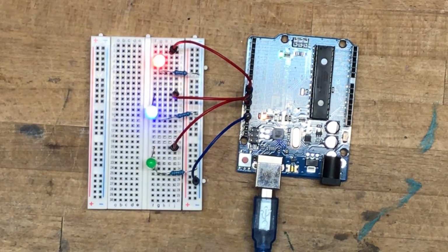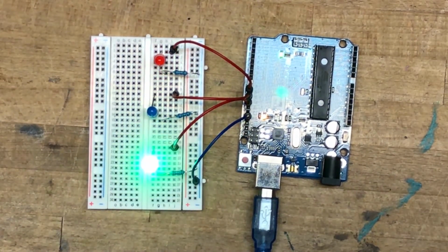So here's the operation of the next little piece of code. This is an example of 2 for loops working in conjunction. So in the last one, the run of the lights was red, blue, green, red, blue, green, red, blue, green, red, blue, green. In this one, it's bouncing back and forth. Red, blue, green, blue, red, blue, green, blue, red. And again, very easy to do with 2 for loops, working forwards and backwards, running through our pins, and everything else is the same. Let's go talk about the code.